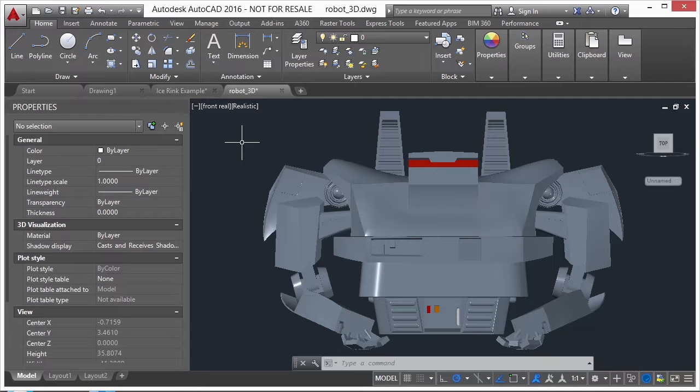One reason you might want to set up a specific view with a specific visual style is because you're going to render an image and you want to make sure that visual style is actually the one applied to your render. In this case, that's what we wanted to do. You also want to use it to navigate, to create paper space views in your viewports, and another option is to print to that specific view.